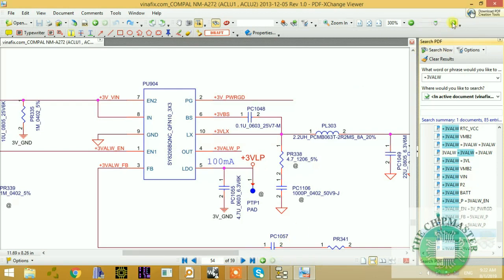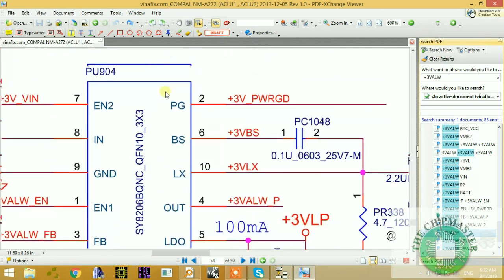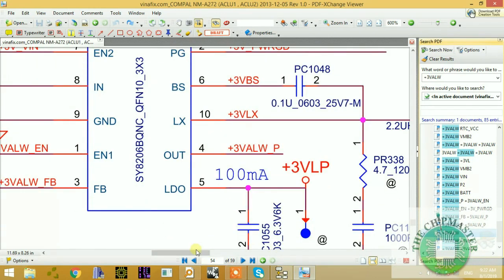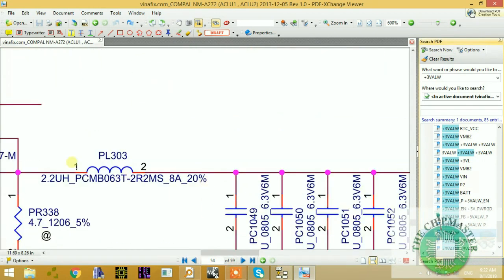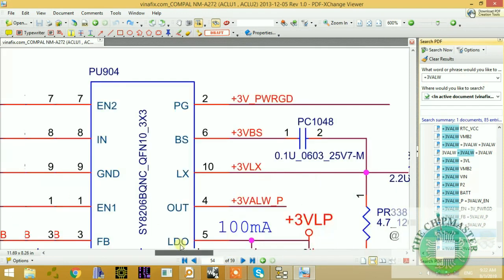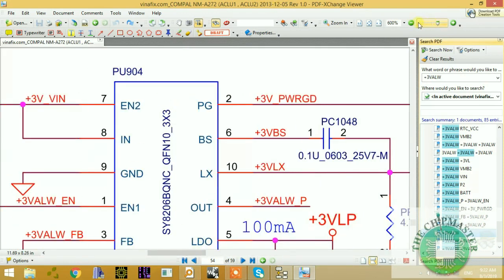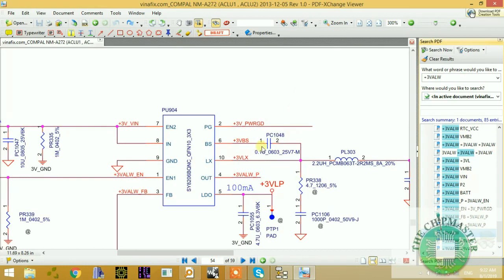This has an embedded PWM chip inside, so there's no upper and lower MOSFET, as you can see on the outside. Only a coil and a chip. It's a PWM chip that's integrated inside of this chip. So let's look at the working conditions of this.